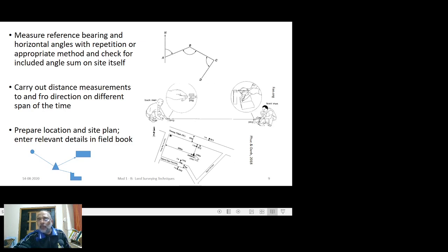Here you can see that with respect to certain important station, two independent measurements are taken in order to define this particular station. This goes according to the second principle of survey, as you remember. Here, this thing assists us in many ways. It will be helping us to plot the network as well as to establish check on the work.